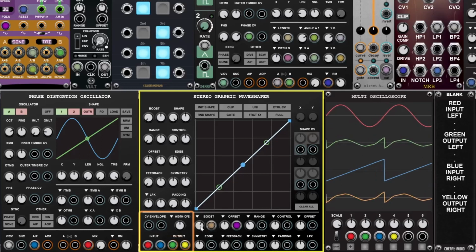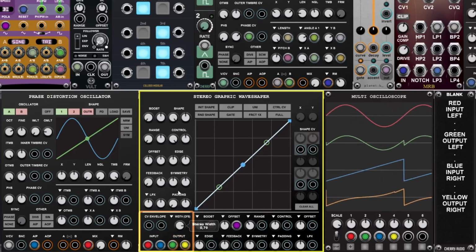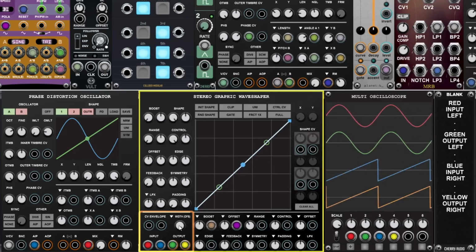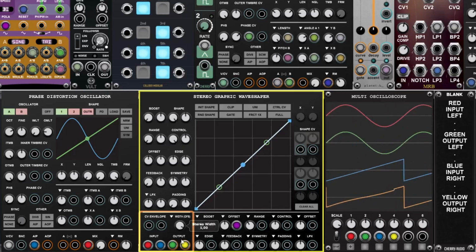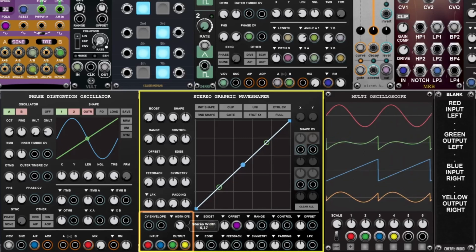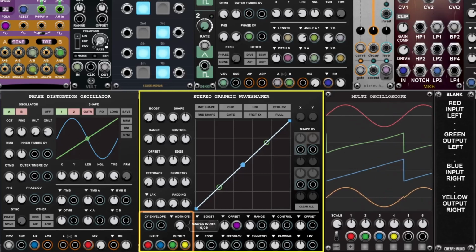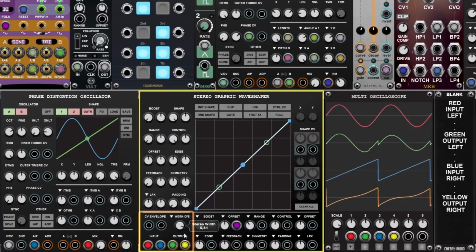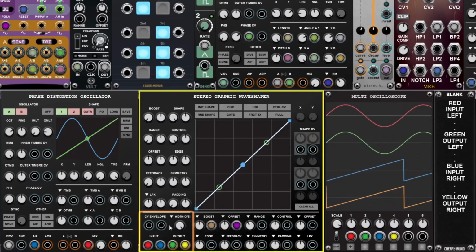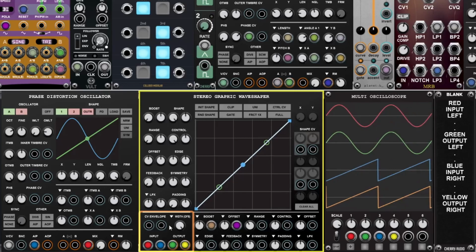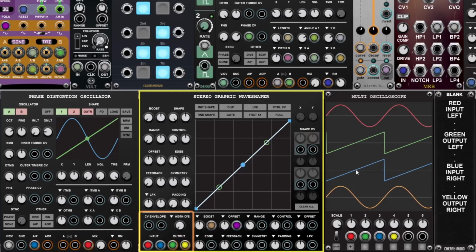When the knob is turned clockwise, the lanes are separated more, until at 100% the lanes have no effect on each other whatsoever. By lowering the values from the 50% mark onwards, the signals become more and more inverted, as the left channel is mixed more into the right channel, whereas the actual right signal is lowered, and the right channel is mixed into the left channel, whereas the actual left signal is lowered. At 0%, there is complete stereo separation again, but the lanes have been exchanged.